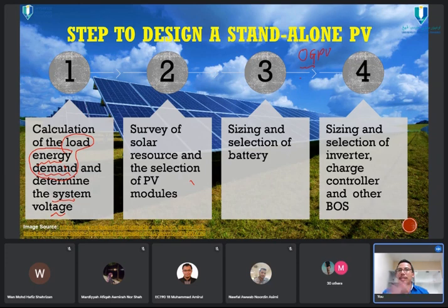In most cases, deep cycle lead acid will only allow 50%. That means if you have 100 Ah, you can actually use only 50 Ah. You may get 55, but you cannot get even more than 60 Ah, even though the battery is declared as 100 Ah. We call that DOD, depth of discharge.